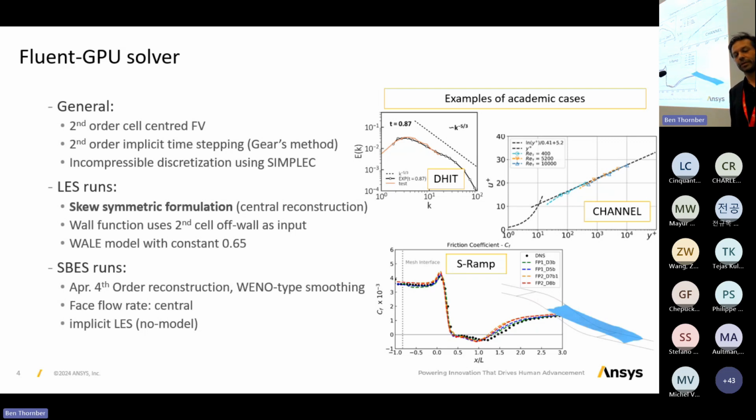I mean, the other way around, we can use the same resolution independent of the Reynolds number for channel flow and for general boundary layers. So keep that in mind. I think it's going to be somehow more important later. We also participate in the wall model LES workshop, and I think also there for separated turbulent flows, we have pretty convincing results at the moment.